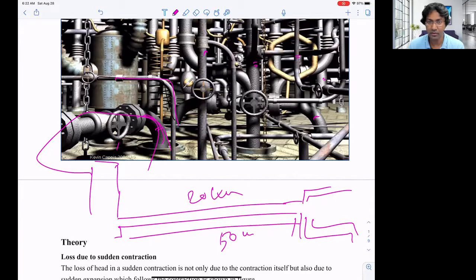We won't lose the amount of water because there won't be any evaporation or any diversion. We're not considering that. We're only considering the loss of energy. So people won't get that much water pressure and that much flow, the force. It will take a long time, and the flow of water will be very slow. So that is a problem. Sometimes you need very fast flow, and we need that much pressure. So you have to be able to calculate the minor losses as well as the major losses.